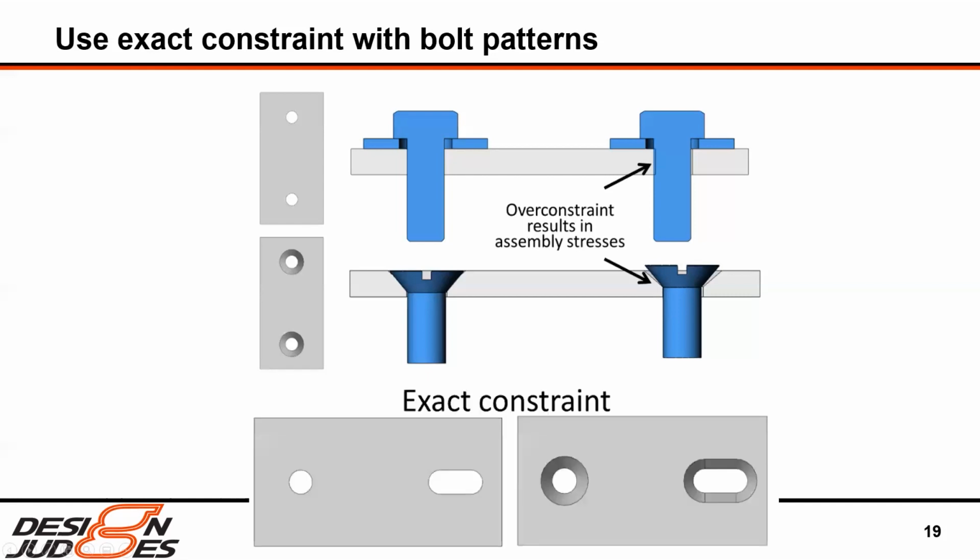So typically what we do instead is use one tight clearance hole, and then a registering feature that specifies the position at one point. And then you can use a slot or some looser clearance holes where you can. The slot is nice because for these plates, they'll rotate and find the spot. And so you can get the exact positioning accurately, and you do not have to ever stress your design just to assemble it.